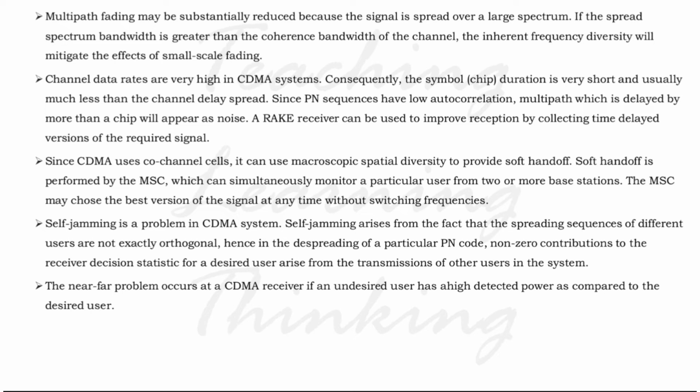Since CDMA uses co-channel cells, it can use macroscopic spatial diversity to provide soft handoff. Soft handoff is performed by the MSC, which can simultaneously monitor a particular user from two or more base stations. The MSC may choose the best version of the signal at any time without switching frequency. And next